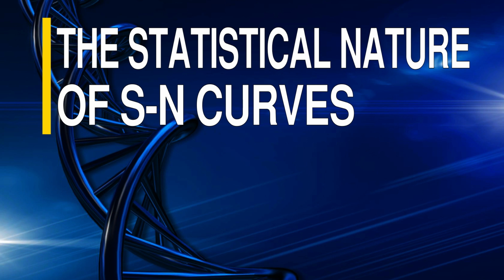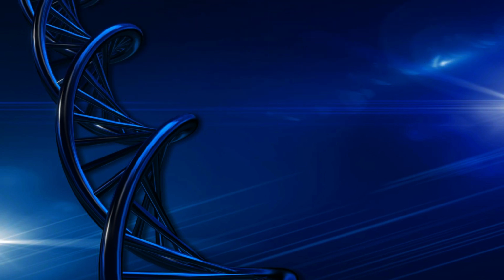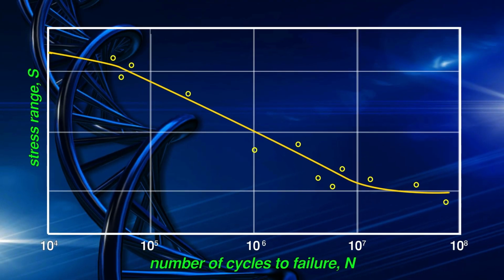Now, if we look at the data from our fatigue test, we can see that there is a large amount of variation in the data. This is typical for fatigue tests even when identical test pieces are used. If we use a best fit SN curve as done here, there is a significant possibility that our component will fail at a much smaller number of cycles than the curve predicts. This test piece, for example, failed at a much lower number of cycles than predicted by our SN curve.